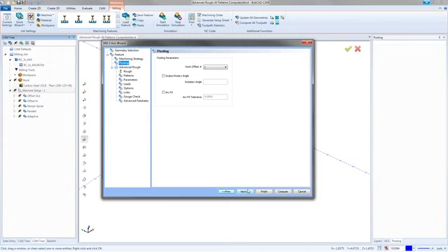The good news is if you forget to turn this on, it isn't something that you have to recalculate the toolpath to kick in. So if you forgot to turn it on, just open the feature back up, click this button on and hit finish. It's really just an enabling option for the post processor to output the program with arcs. So if you forget to turn it on, just ignore it. If you go in and turn it on, you don't have to compute it.